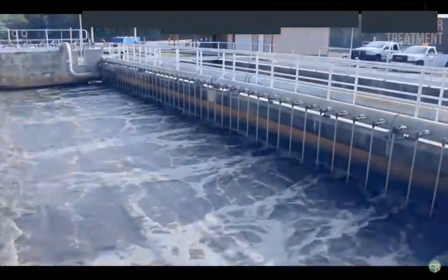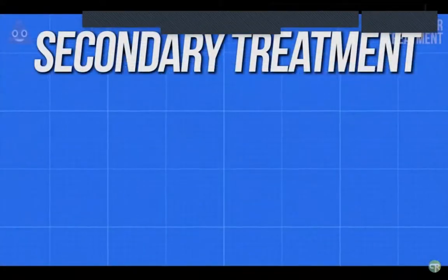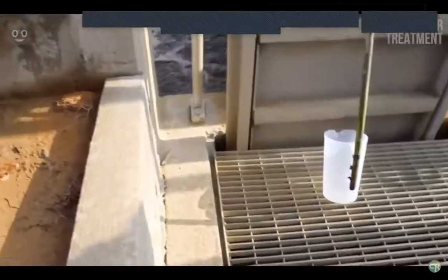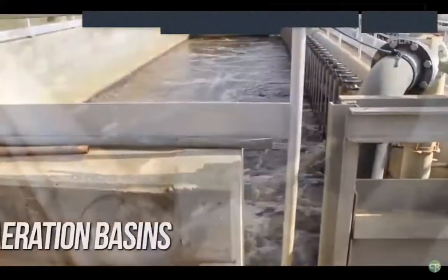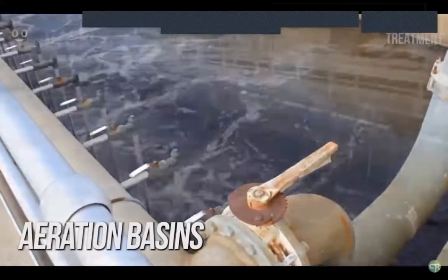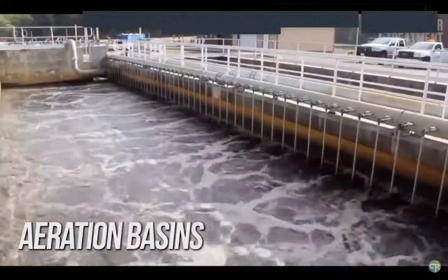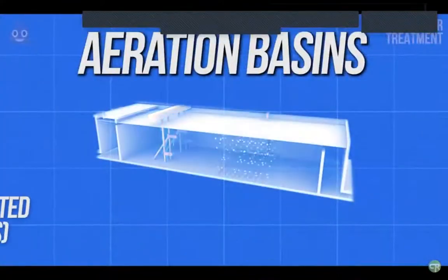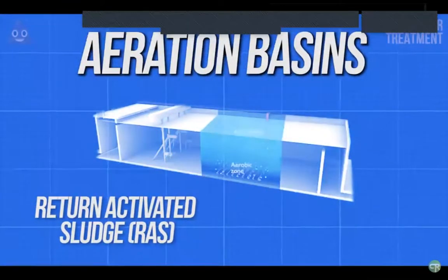Now begins the process of secondary treatment, the sole focus of which is to significantly degrade the biological content of the sewage. In many cases, this process starts with aeration basins. Effluent flows into the aeration basins, at the bottom of which are hundreds, if not thousands, of tiny air blowers that create bubbles through the water. The water is pumped into this tank along with something called return-activated sludge.